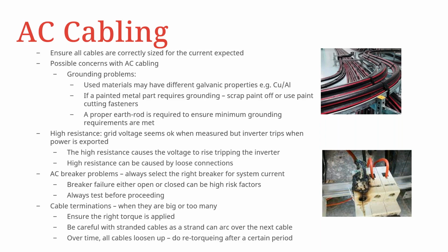Also, another thing that can occur is your AC breaker problems. So always select the right breaker for the system current. Breaker failure, either open or closed, can be high risk factors. Always test before proceeding. So always test your breakers and everything before proceeding with your connections.